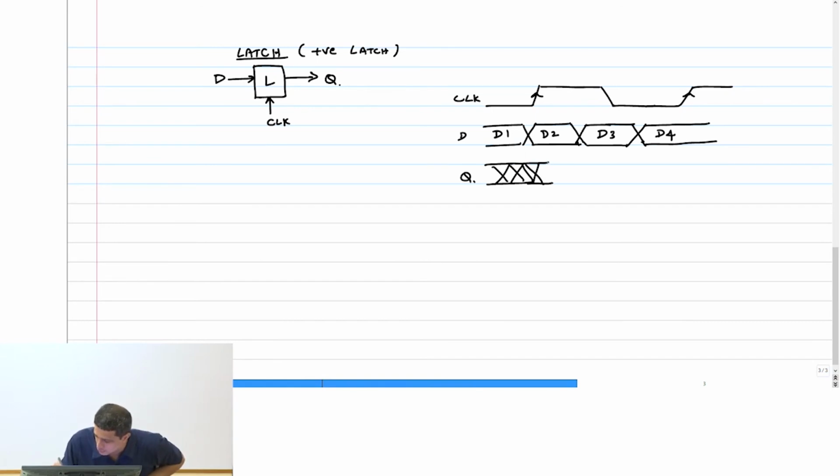And so as usual, you will have some early transitions. This delay is caused by, is triggered by what? By clock or data? Remember, my data changed before the edge. The latch was opaque at that point. Then it became transparent.